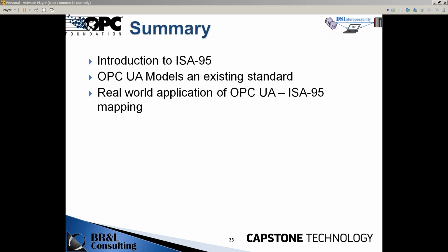Every device has computing power in it. And with the OPC UA 95 specification implemented, each device itself can be self-describing. You can say, I am this type model, I am this product code, this model, here's my parameters, here's my base level horsepower, here's what my real-time values are.